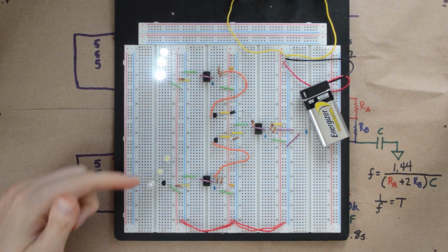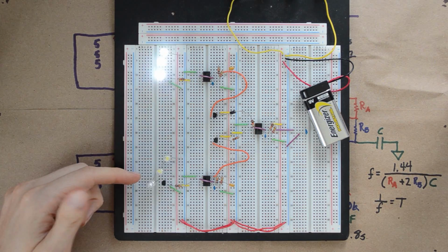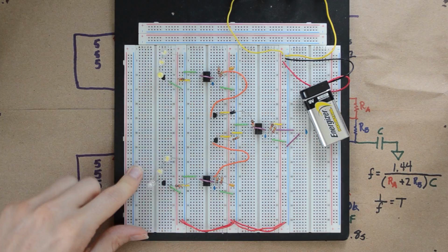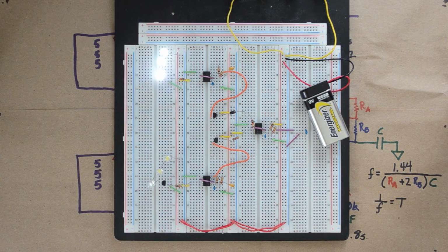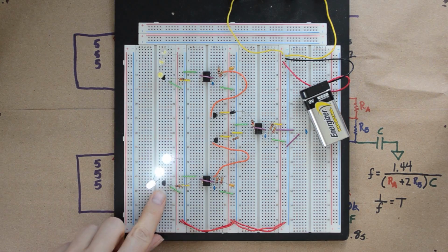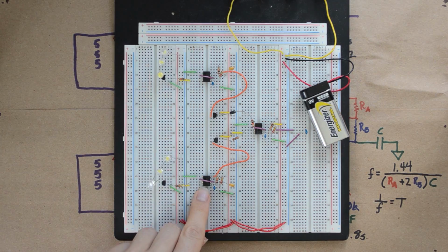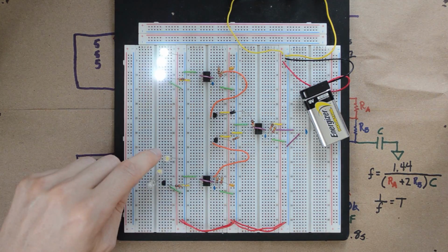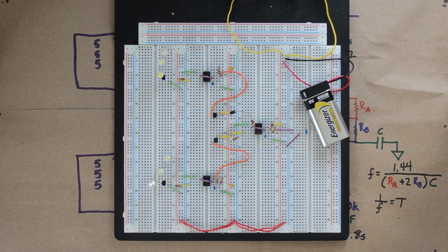Remember, if you just want to do one LED, all you have to do is throw one LED in there and then calculate what size resistor you need to take care of that LED so it doesn't pull too much current. And then all I've got that is in line with an NPN transistor, so that every time this guy here goes high, it turns this NPN on and allows current to flow from the LEDs to ground, thus turning them on.